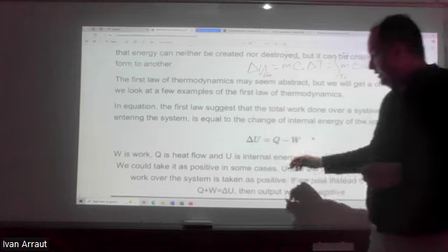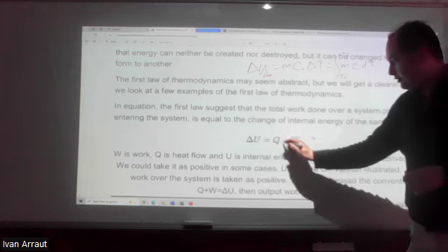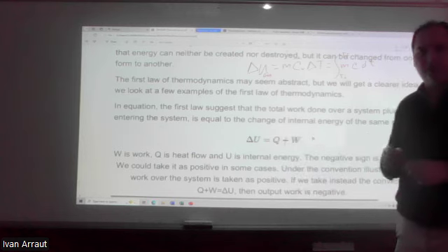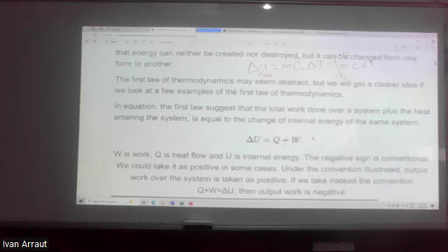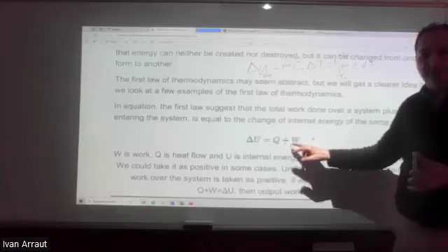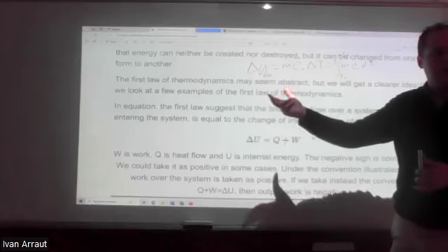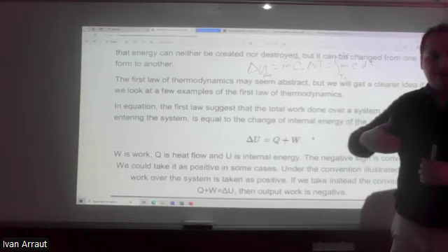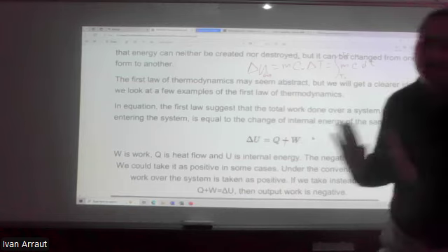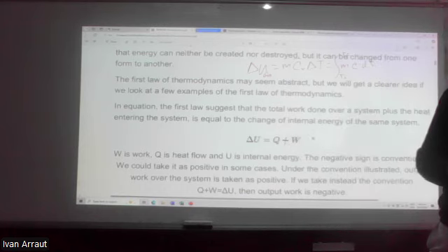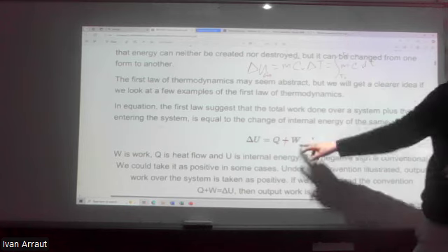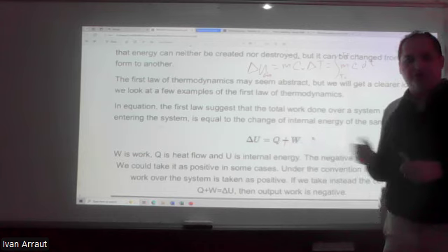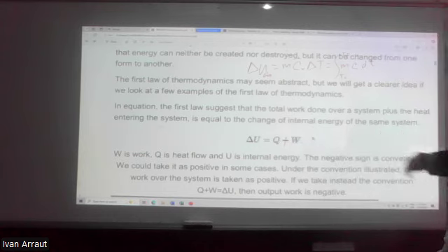But when you use enthalpy, then, summarizing this part, there is conservation of energy here. Heat, normally, we will take with this convention as positive. Later, I will share more. But we will take work going out from the system as negative, and work entering the system as positive. If I push a piston, I am inputting energy to the system, so I take that as positive. If the piston is releasing work, it's losing energy, so I take this as negative. I like this convention. It's more logical from the perspective of physics.